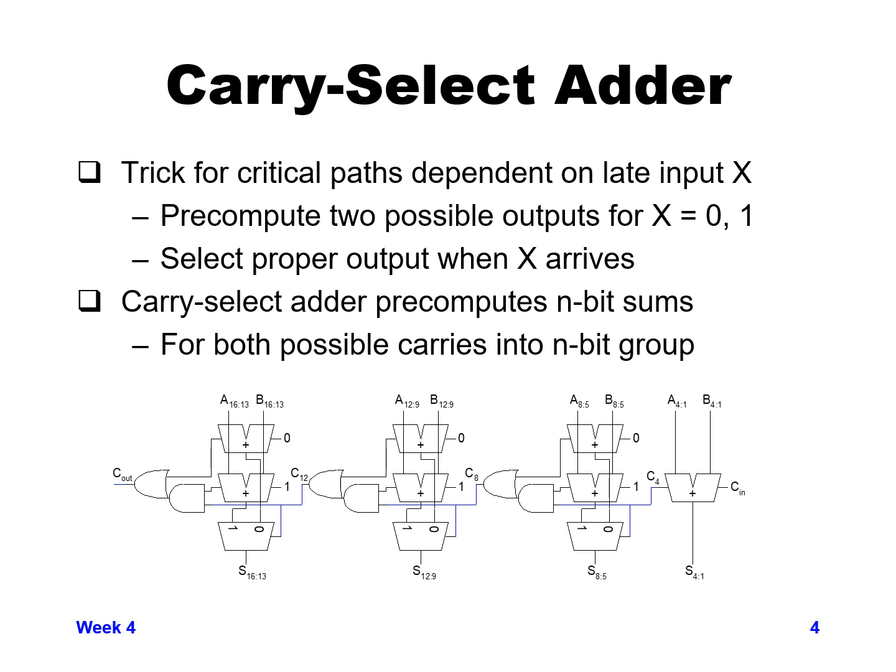Now it isn't necessarily all that useful for bits, let's say 8 through 5 and 9 through 12, because those weren't our critical path for the sum anyway. But you might want to use it for your higher order bits, because the sum 16 through 13 would have required the value of carry sub 12 to come in and then ripple through 4 bits in order to get the final sum sub 16.